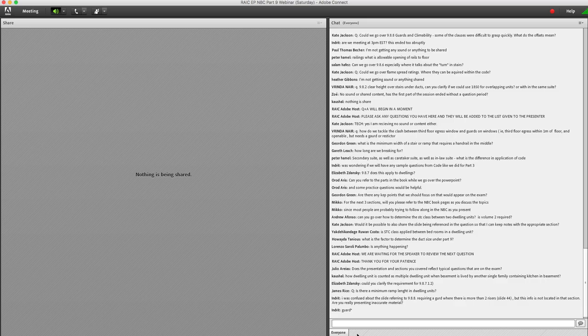There was another question on the clear height requirements under beams and ducts. Where can the clear height be 1850? This is again in that same NBC Article 9.8.2.2. The clear height over stairs, under beams and ducting, and in secondary suites shall not be less than 1850. This is often applied to basement suites where you just don't have that additional space, so there is a relaxation of the requirements.